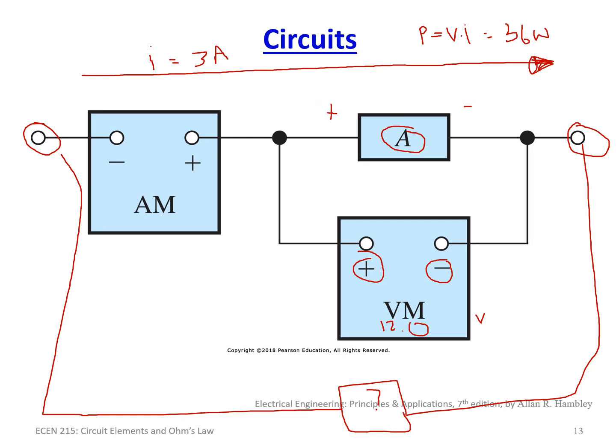So what do you think is on the amp meter screen? Notice the direction of the amp meter. The amp meter here we have as negative and positive. Now, do you think that really matters? Does the amp meter care? The amp meter actually doesn't care which way you do it, but if you're reading it for the purposes of knowing the current, it does matter.